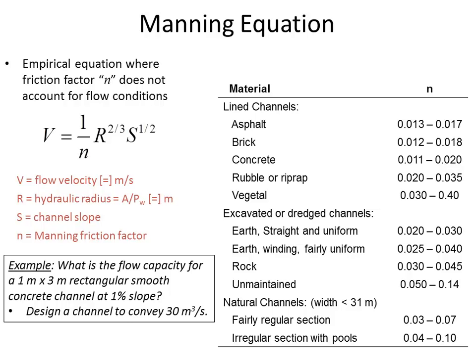If you're not sure how to get started, probably the simplest approach is just to select some width of the channel or some depth that you'd like to have, and then find out what the other parameter will be.